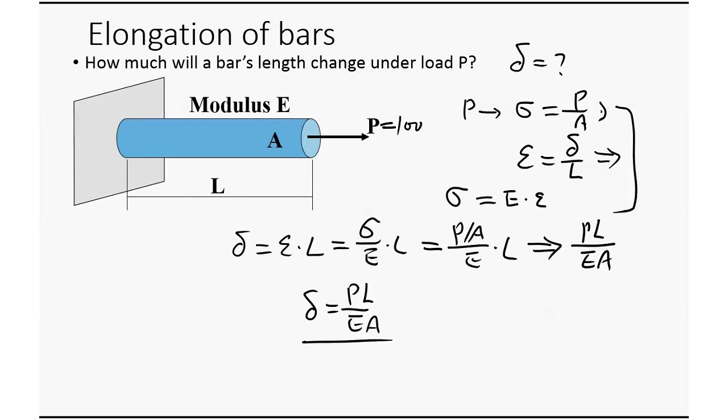You have a long bar. If you cut it here, if you cut this cross section, draw it here, all the stress here, this is sigma. It's pretty uniform. The force is uniformly shared in this cross section. So you have to assume this bar is very long. We're not talking about this area, because if you look at this corner here, there's no stress at this edge. So it's very non-uniform here. We talk about somewhere far away from the edge effect.